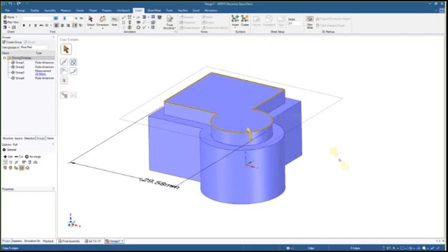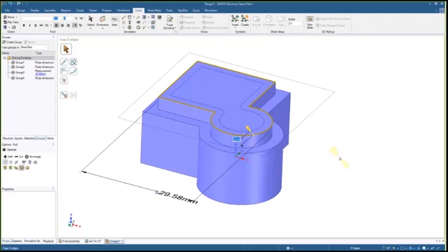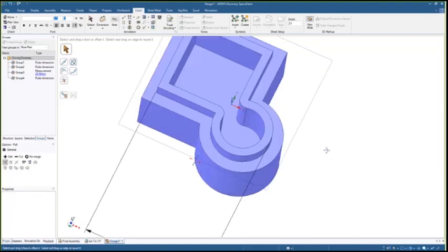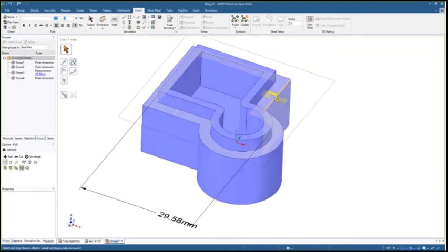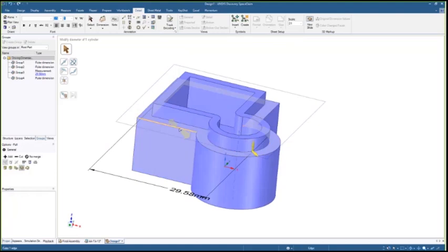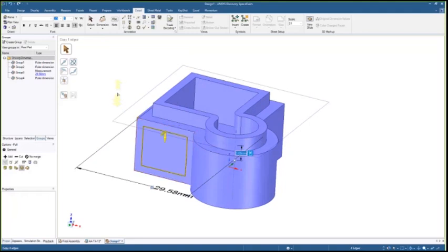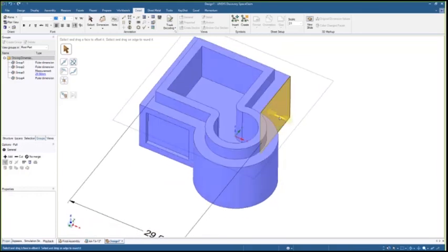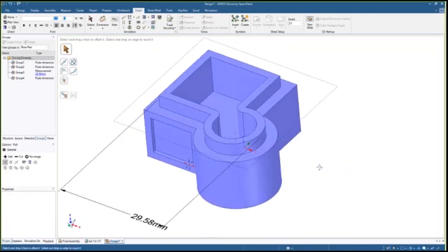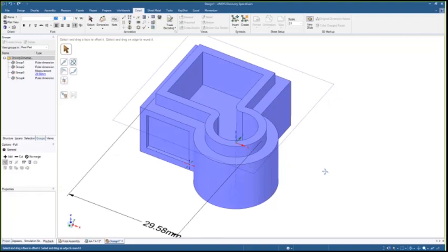And if I switch to this direction, I could also copy in that way. Now I have new geometry that I can pull up or pull down, maybe to add some coring. So one great way to reuse geometry that you already have is with the pull tool, using edges and copy edge, picking the right direction, and then pulling that in. So you'll notice that all of this geometry was created with just sketching a rectangle and a circle, and the rest here was done with pulling.